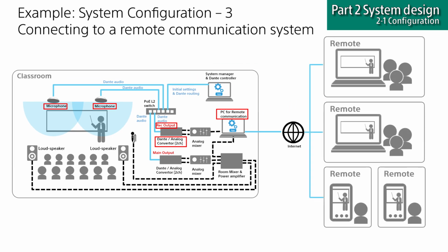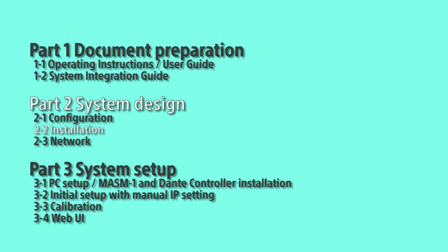But there are some concerns of side effects such as echo return when using beamforming microphone with conference system that has echo cancellation capability. We Sony conducted some tests to see the side effects. As a result, side effects are within affordable level. But please be sure to test at your actual environment before installation. In this section, I will explain the tips related to installation.